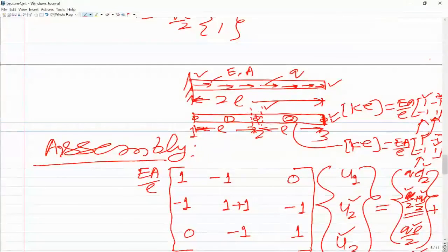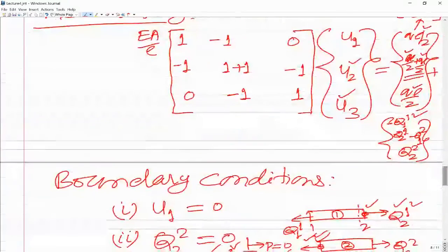Essentially, if you think of this as a lumped load vector, the total load along the axial direction is QL, which is equally divided between the two nodes of the element. But the second node gets contribution from the first element as well as the second element. So that is how QL by 2 plus QL by 2 comes out as QL. So means we can say that this part of the truss will have the maximum axial distributed load concentrated at that point. Yeah, right.